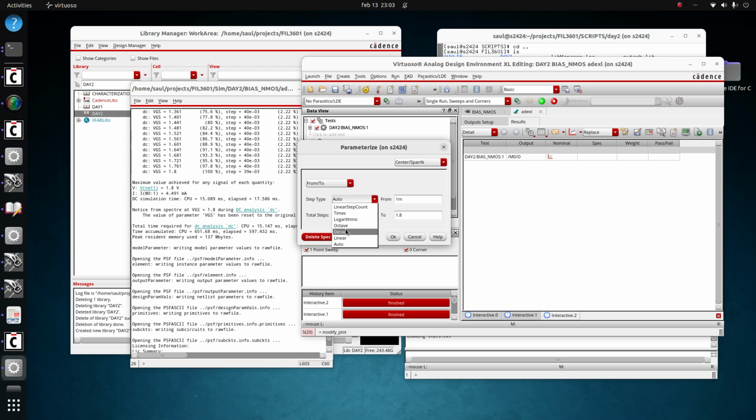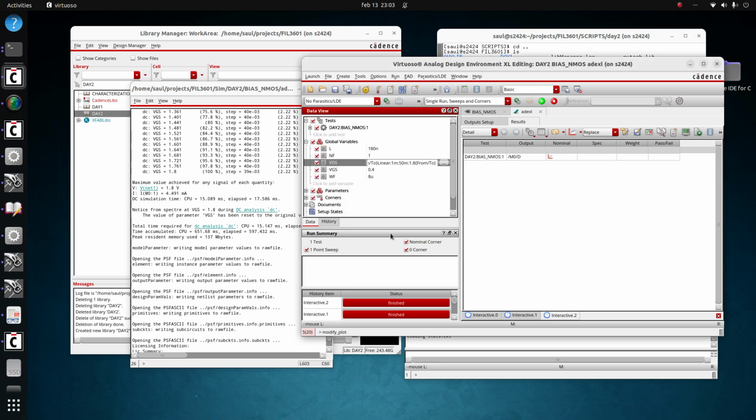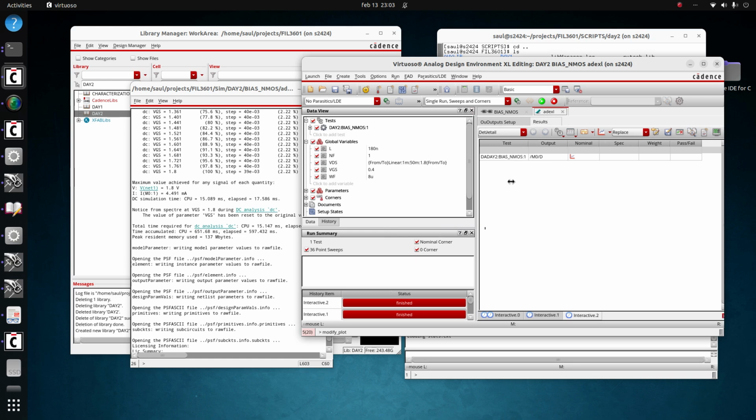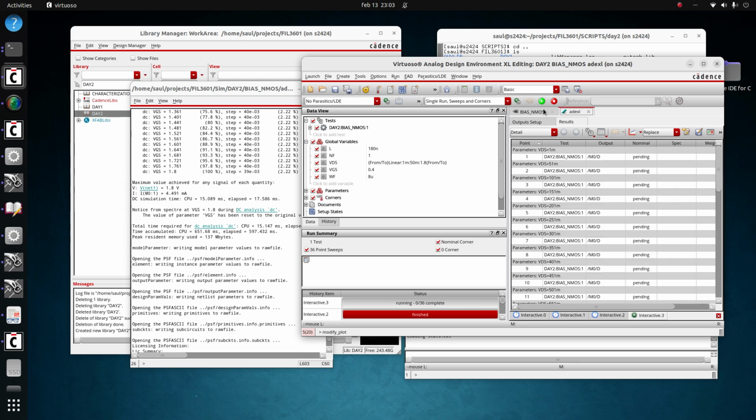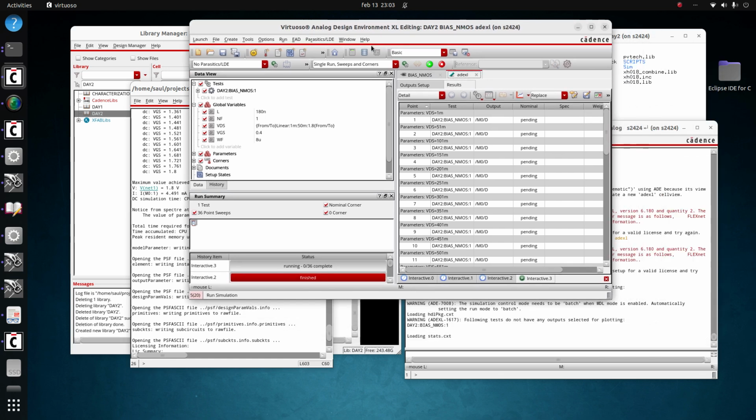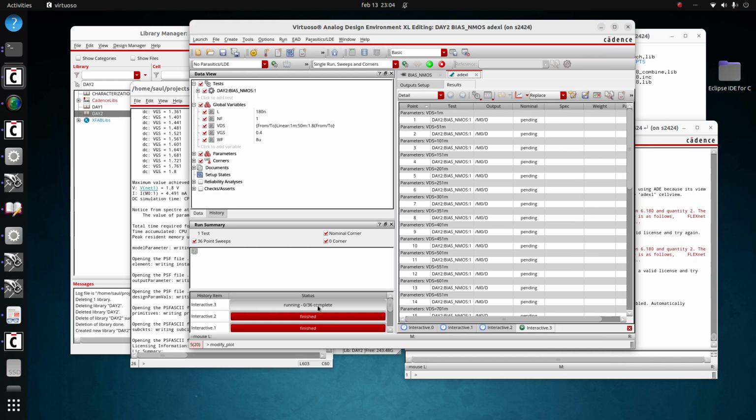And then I want to use the cuts here, or we can use just linear for the first time. It was linear, and then let's use like 20 millivolts or 50 millivolts VDS. Okay. And then it automatically creates this configuration for VDS. Now I run it. And it is a sweep of 36 VDS points here, and it's going to do it one by one.